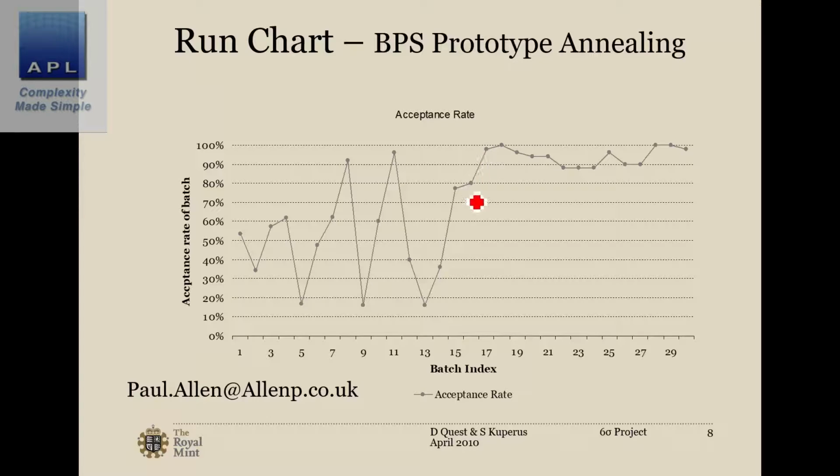Look at this. You've got wild variability. Now, if you think about this, this was a tolerance, the capability we talked about earlier. You see, it's wild variability. You haven't got process capability. In this case, though, this is just the better graph, because this is the acceptance rate. So they wanted to be above 85%. That's where they thought they could be. They wanted to be above 85%. But look at this thing. It's sitting up here at 95%.